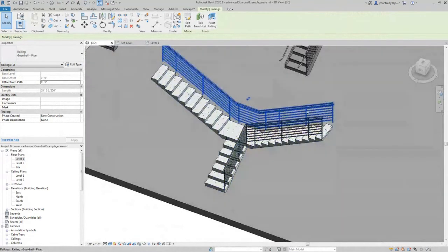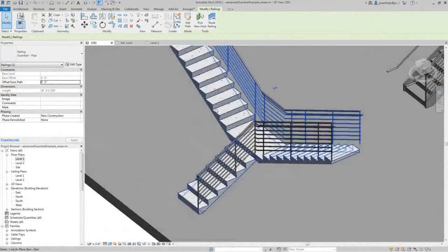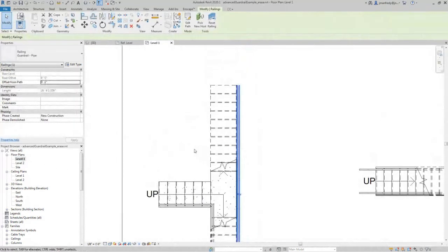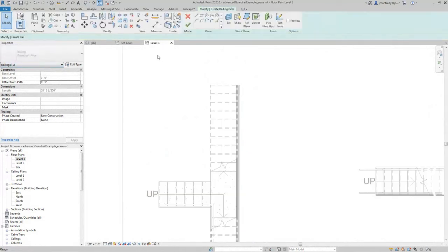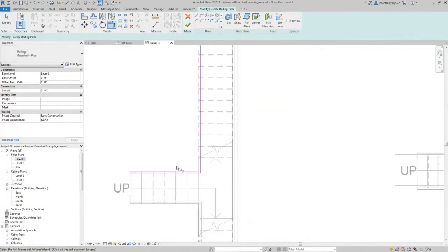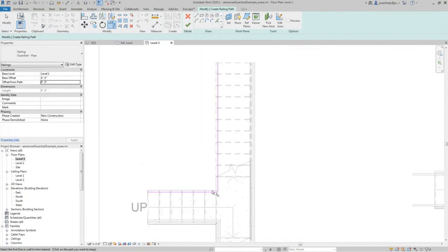So it will make that railing continuous all the way across. You'll have to draw this railing on the inside edge. So if I'm using, let's say, a guardrail design, I can say, give me a railing and use the same style pipe, and say, here, 2 inches away from the edge, pick it here and pick it there and connect these two together, right? I can do that and just trace those edges, and I want it to be 2 inches back. I like the way that looks, I think.